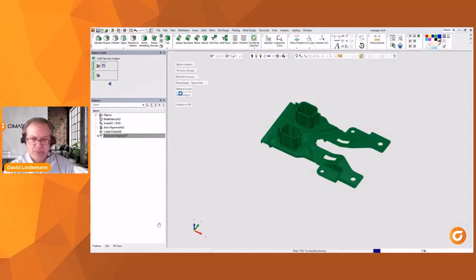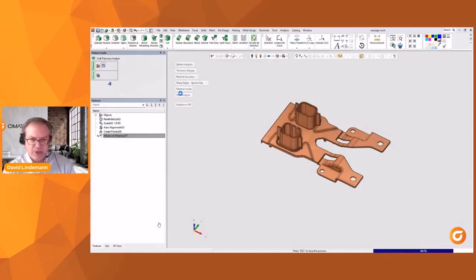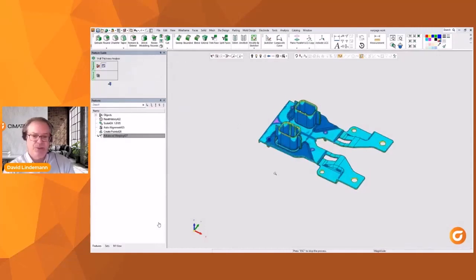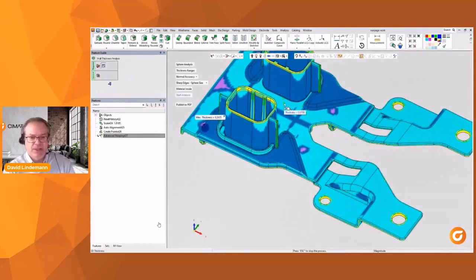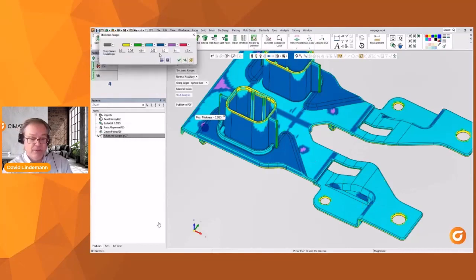So what this tool will do is wherever I pick on the part, it imagines a ball that would fit inside all those surfaces. So it's going to tangentially touch every nearby surface within that range. So see the cursor as I move it along the part? Those wall thicknesses are pretty consistent. Then other areas that were thicker, areas that I knew were thicker ahead of time actually, are still that same thickness as well. There on the left, underneath the values here, this pull down I got, you can kind of see the max thickness.